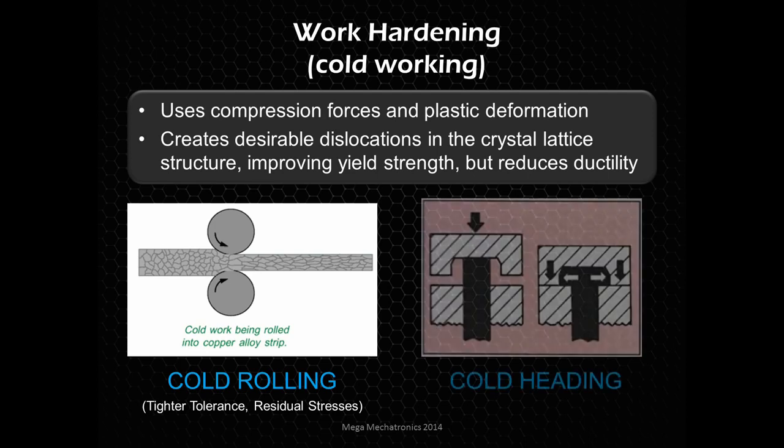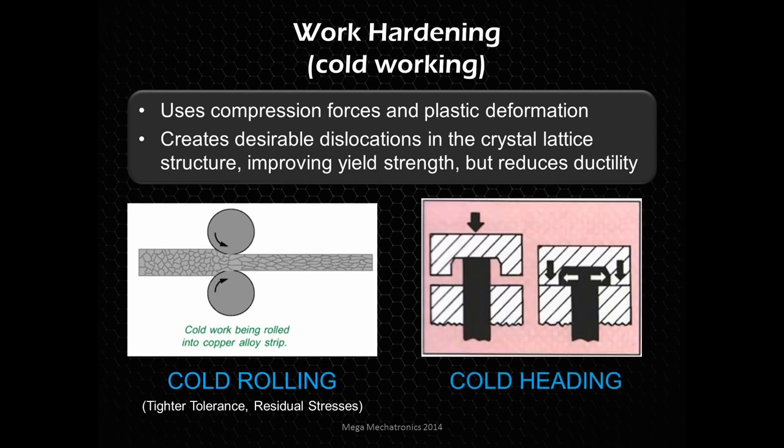Cold heading, this is a process of putting the head on a bolt. You see that die comes down and plastically deforms it, and it does work harden that head and make it a little stronger.